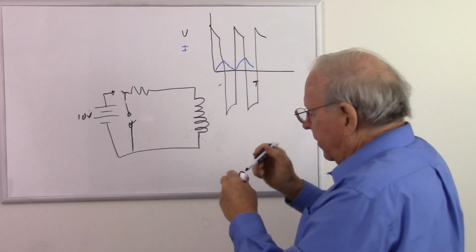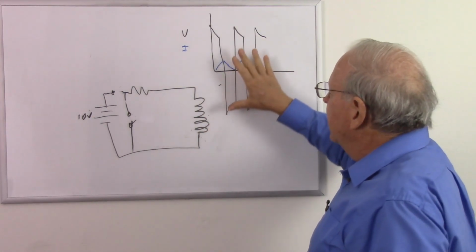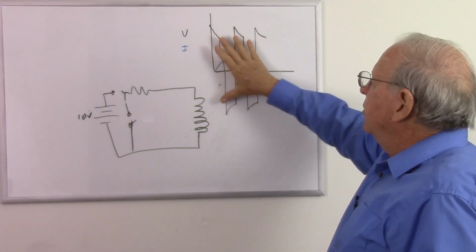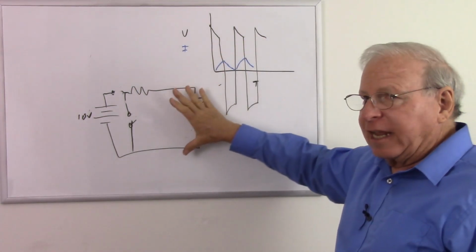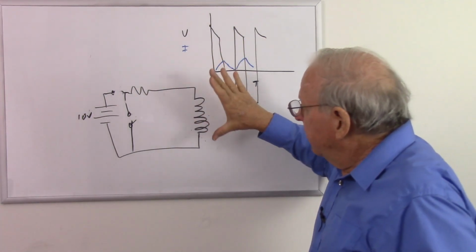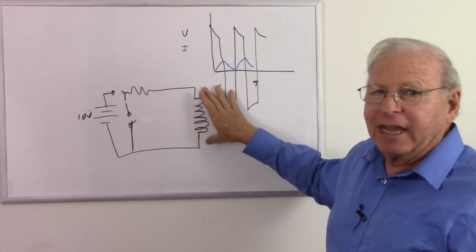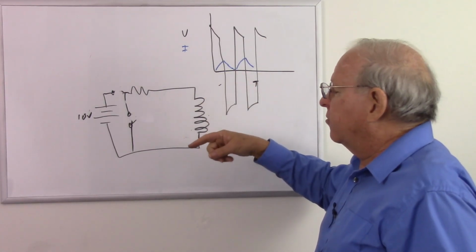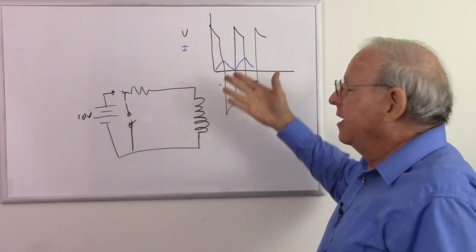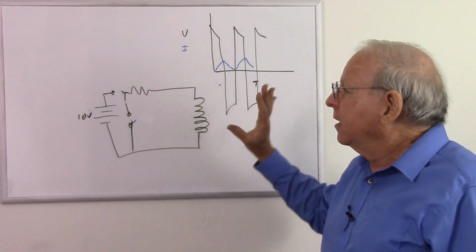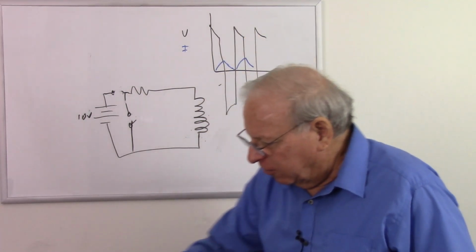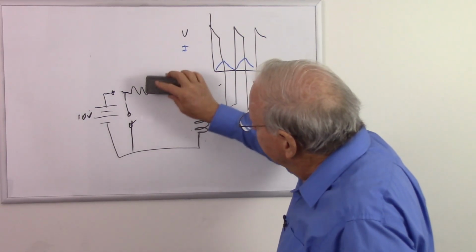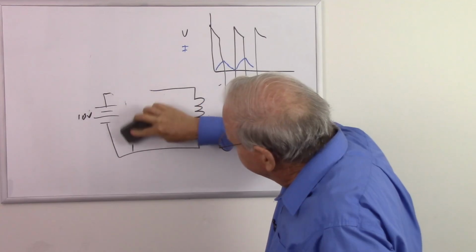And so I am now putting alternating current across it. And I showed that as I did this at lower frequencies, I got less average pushback from here. So I had less inductive reactance. But if I did it faster, I got more average pushback, increasing the inductive reactance. Well, I told you that just to tell you this. I want to make a little slight change in that.